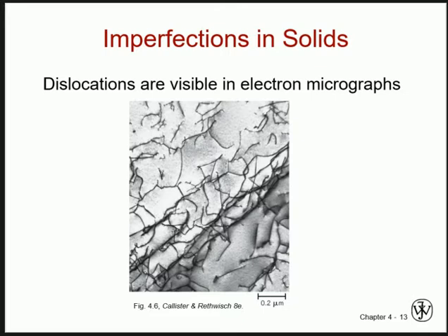And the easiest direction in which the material can move is called the close packed direction or highest density direction. As we have seen in the crystal structures, the directions in which the atoms are in contact with each other have the highest density of atoms. So whenever a material deforms, the atoms will move in a direction in which they are in contact with each other. That's why defining various directions at the atomic level is important, because we need to know in which direction the atoms will move when the material is deformed.